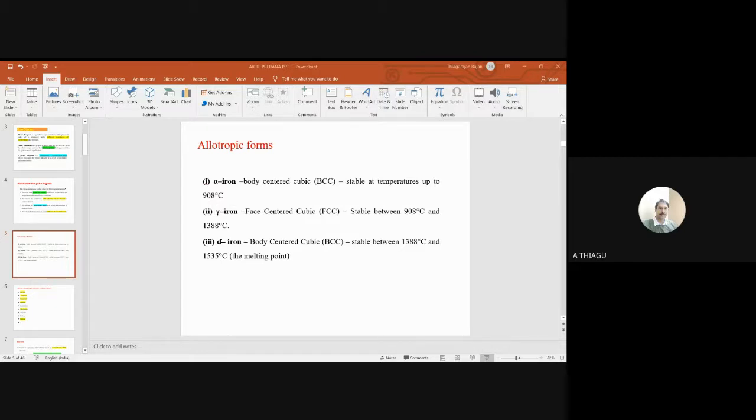Now look at the first category, gray cast iron, because the appearance is gray in color. It looks like flakes of carbon. We can say it is graphite, and graphite is nothing but carbon. Flakes of carbon are represented in the microstructure analysis. Gray gets its name because the fracture surface appears gray, so we call it gray cast iron.